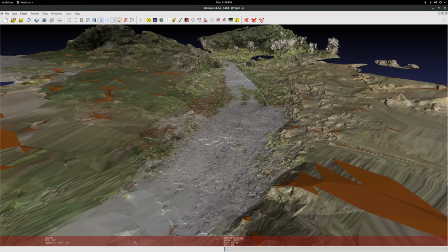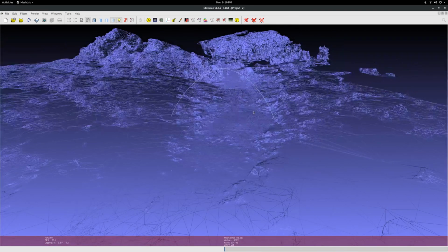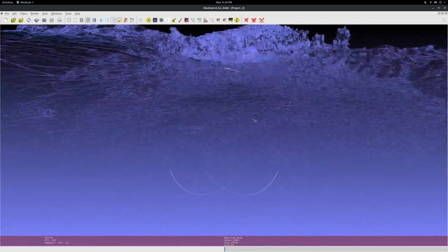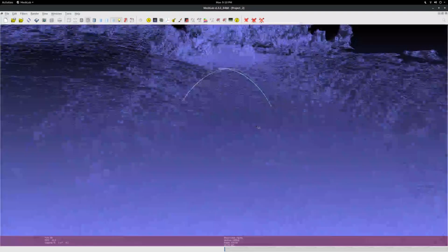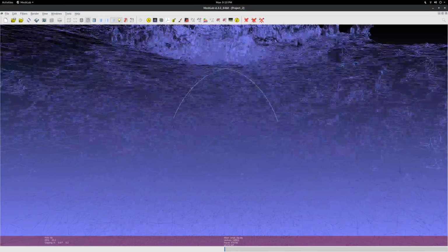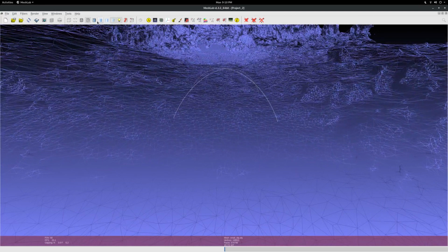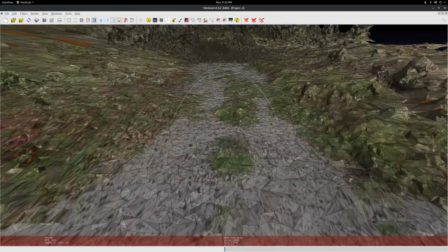Those 2 pieces of software both have great tutorials, and I basically just did what their tutorials tell you. You do the OpenSFM tutorial, then you export to OpenMVS, and then you take that exported file and do what the OpenMVS tutorial says to do. It's all pretty straightforward. And what you get out is a textured mesh. I think there might be some compression artifacting on my viewer, but you can see that this is not just a point cloud, it's actually a mesh of lines, and that might be a nice view there as well.